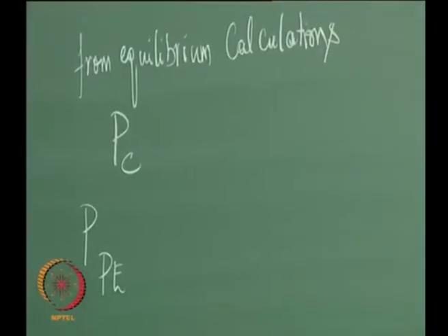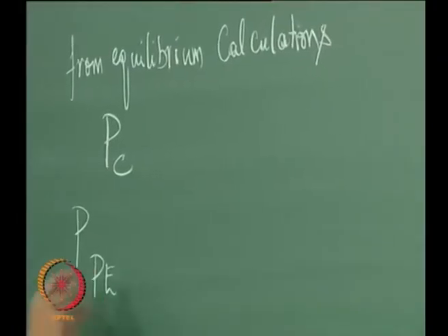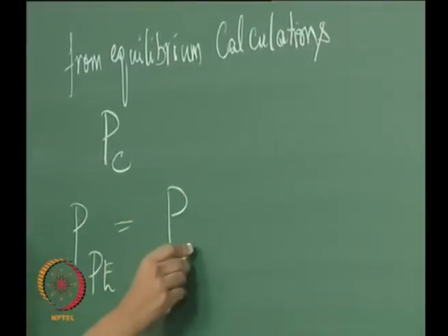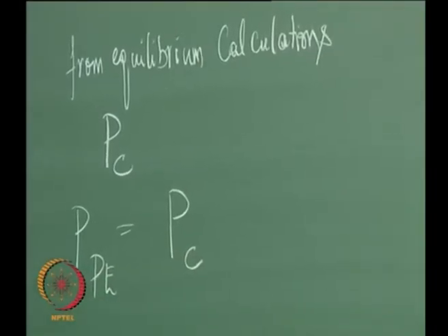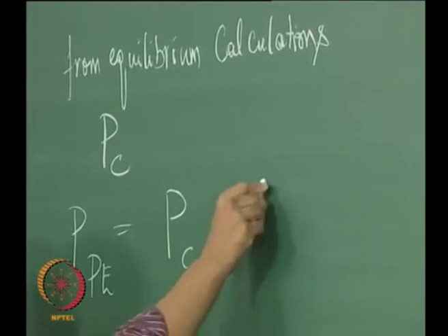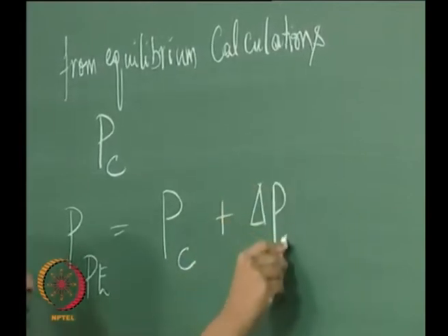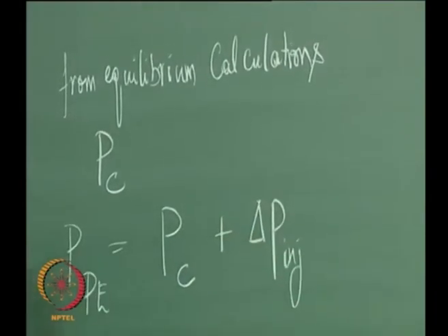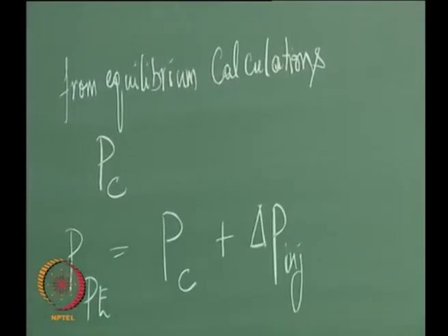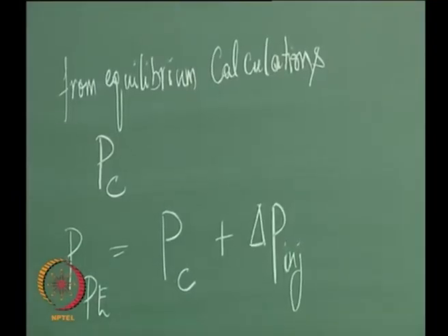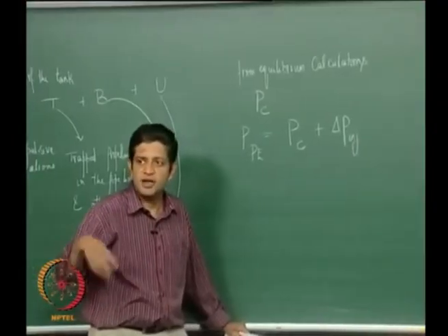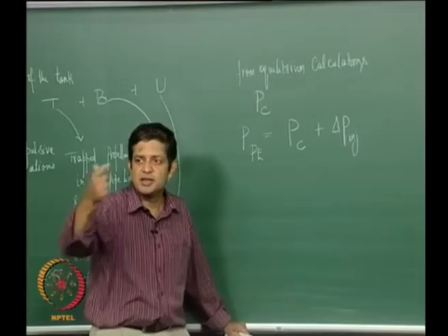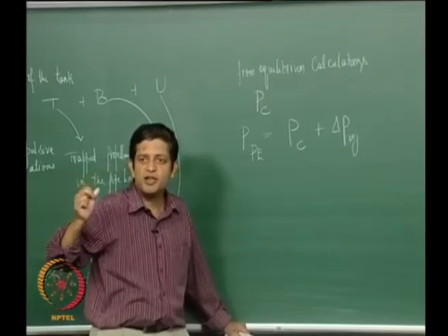So, this pressure at the pump exit will be the chamber pressure, plus the pressure drop in the injector, fine, and then there is pressure drop in the recirculating chamber, right. It is a coolant jacket with very fine tubes.